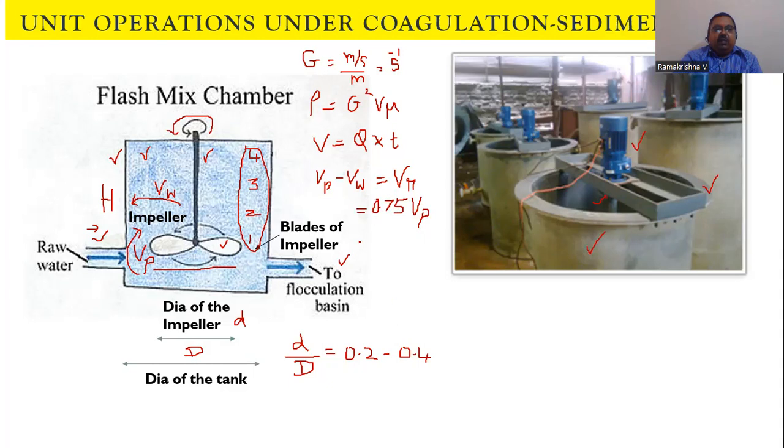And another one is because the object is moving in an immersed fluid, so you will have a drag force. The drag force arises because the impeller is moving with some rotational velocity. So we are having a force related to drag force. Power is also calculated as force into lever arm. The drag force into lever arm we are going to calculate, which is equal to